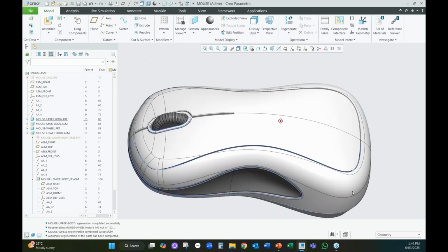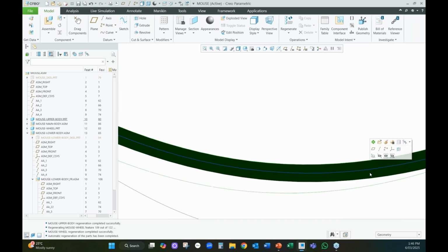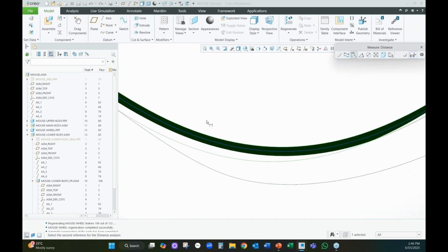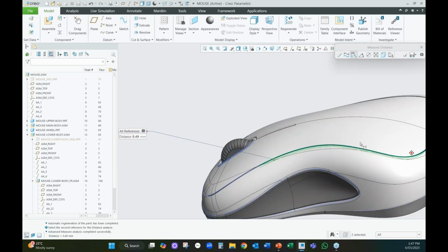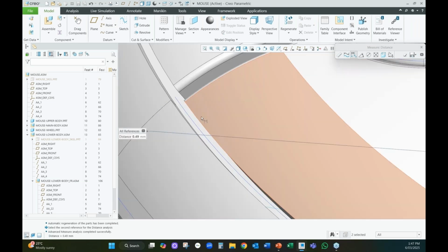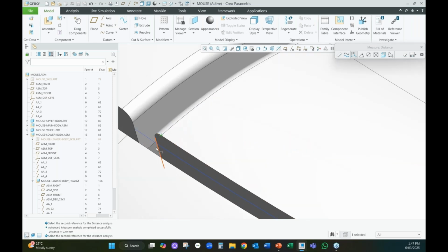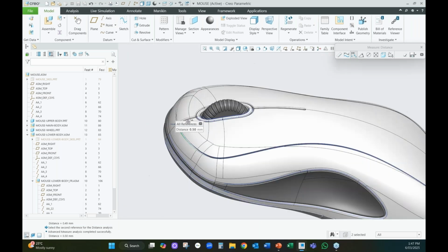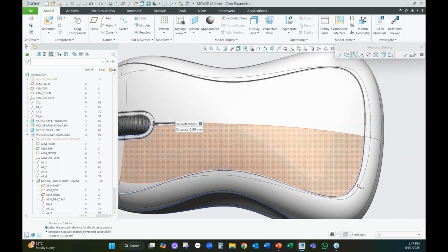The big advantage of this, though, is because we constrained from the top level things like our part line gaps. If we come in here and measure, we've got a 0.5 mil part line gap, and even though we made that high level design change, we have the confidence that a uniform part line gap is maintained regardless of the geometry that it cuts through.